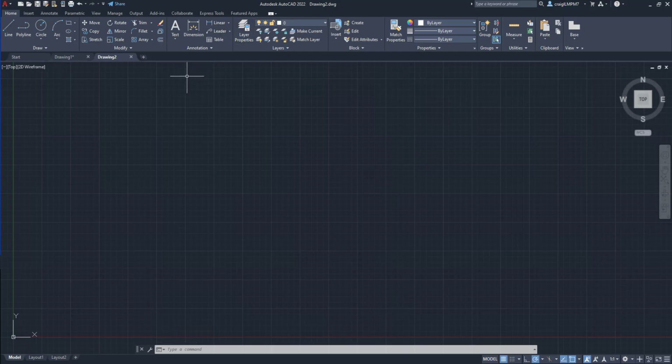So you can just hit Control S or save up here, and it'll save your drawing for you. I suggest you rename it after every 3 saves. You know, just put version 1, version 2 or something. So if something goes bad, you don't overwrite the previous files and you have something you can go back to.